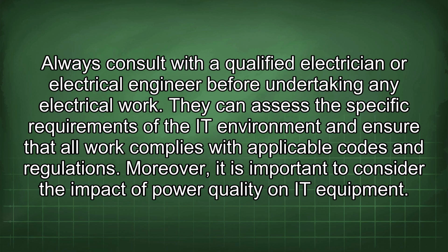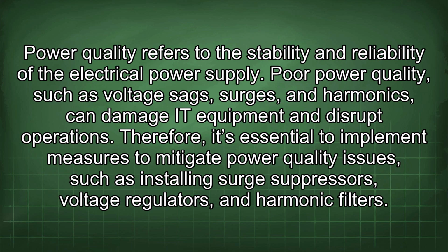They can assess the specific requirements of the IT environment and ensure that all work complies with applicable codes and regulations. Moreover, it is important to consider the impact of power quality on IT equipment. Power quality refers to the stability and reliability of the electrical power supply. Poor power quality, such as voltage sags, surges, and harmonics, can damage IT equipment and disrupt operations.